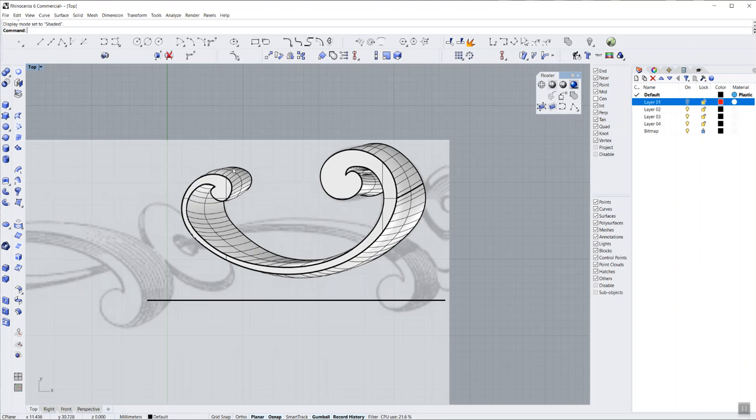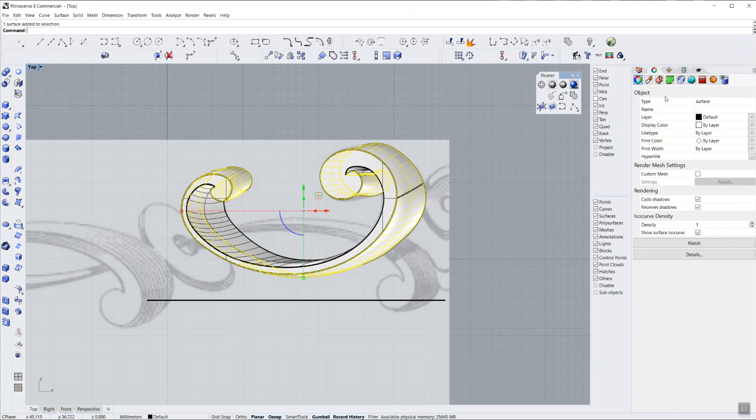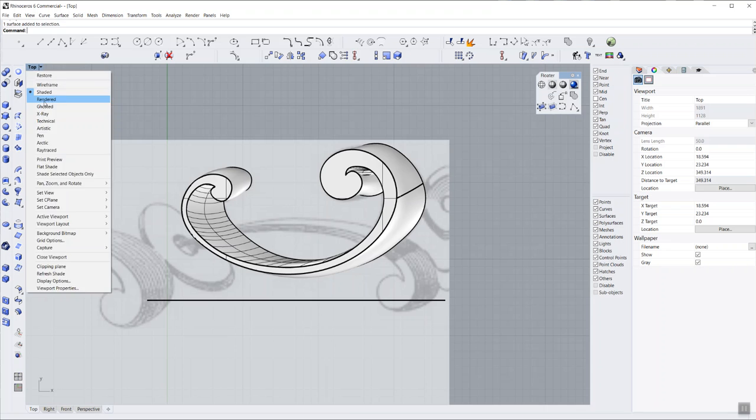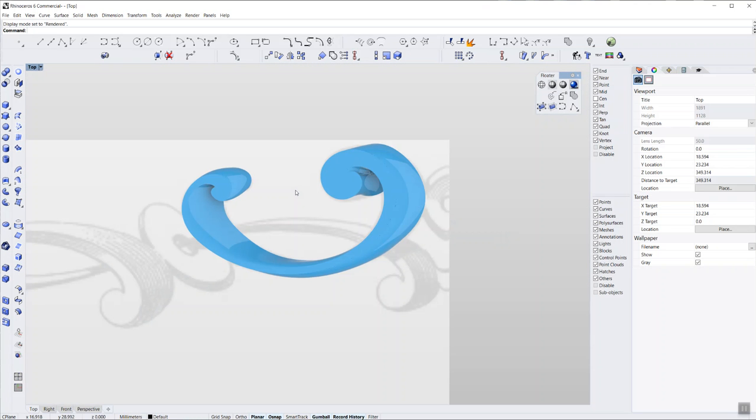We can see that we've now got the bulge and the concaveness, and also it appears to be bulging here. One thing I do, I get tired of all the iso curves, so I'll come into material and I'll say turn off those iso curves so I can get a good look at it. And then let's take a look in the render view. That's starting to look pretty darn good.